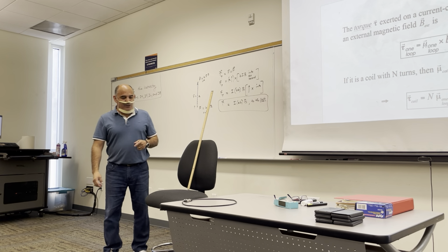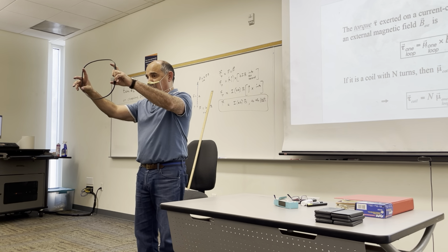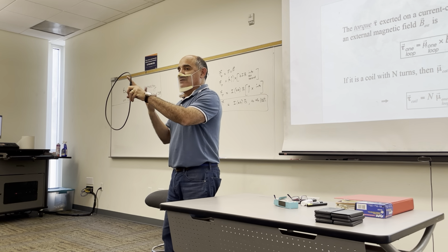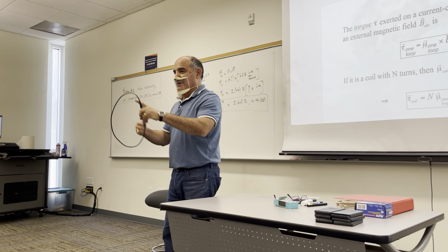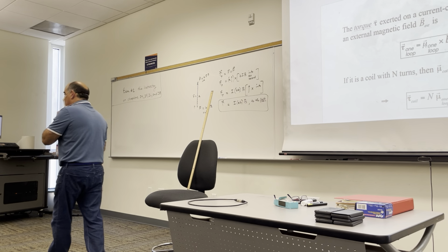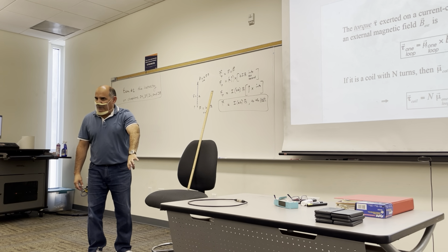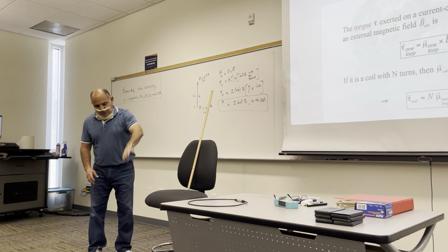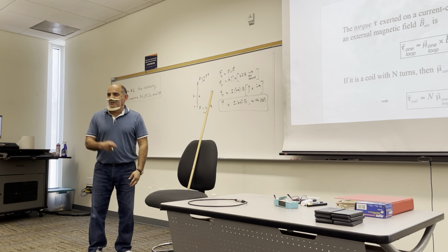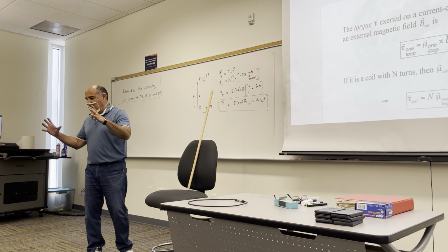What they do over there, though, is they don't spin the coil. The coil stays put, and the blades of the turbines spin the magnet. Well, what matters is the relative motion between them. So they spin the magnet instead, and the coil stays put, and that's how electricity is generated. So there you use the gravitational potential energy of the water as it comes down. It turns into kinetic energy, which hits the blades of a turbine, which then turns, and that's attached to the magnet that's moved in the presence of a coil.